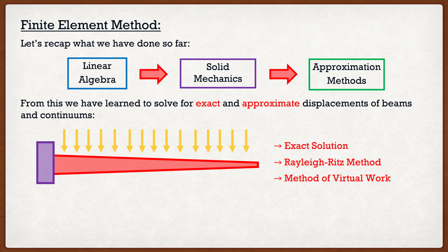If we were to look at this beam, it's not too much different than the other beam, except that the cross-section changes throughout the length of the beam. This poses a bit of a problem because the moment of inertia, of course, will change with it. Remember that the moment of inertia is a cross-sectional property, so if the cross-section changes throughout the length of the beam, so will the moment of inertia. You may be saying, all right, Clayton, no problem. I can solve the beam using this equation, and I'll just take into account that the moment of inertia changes throughout the length of the beam.